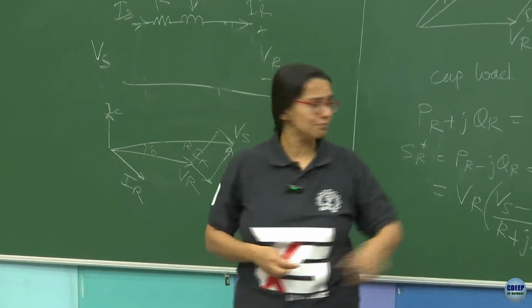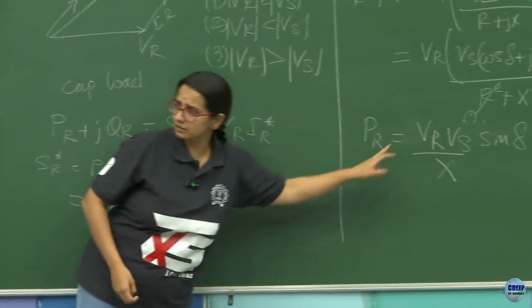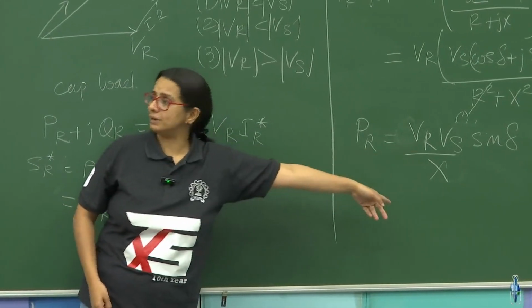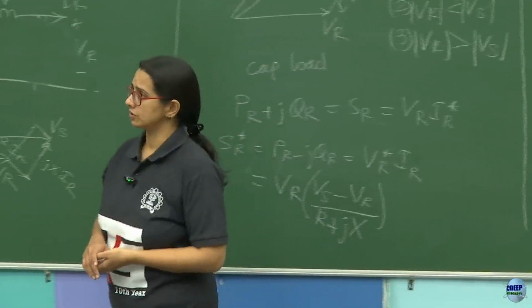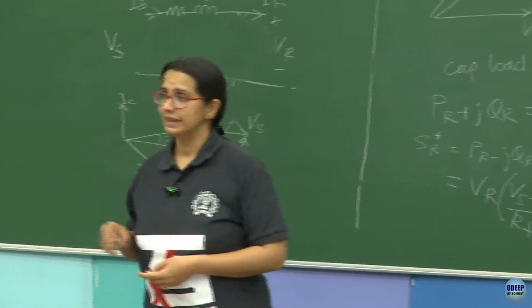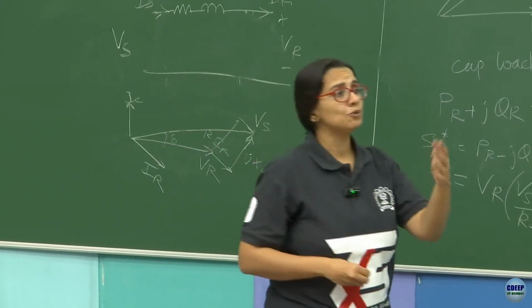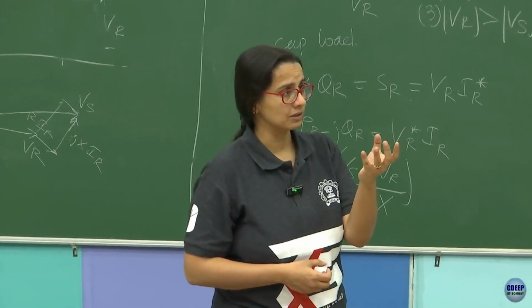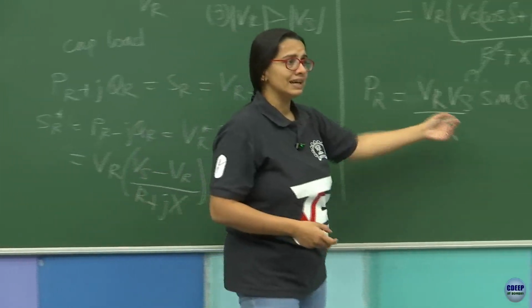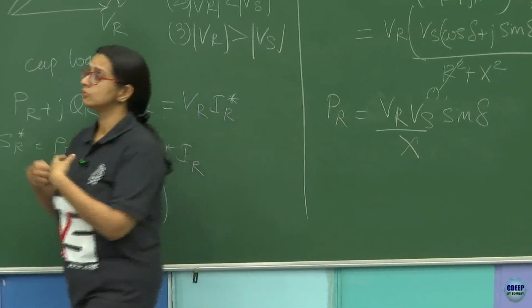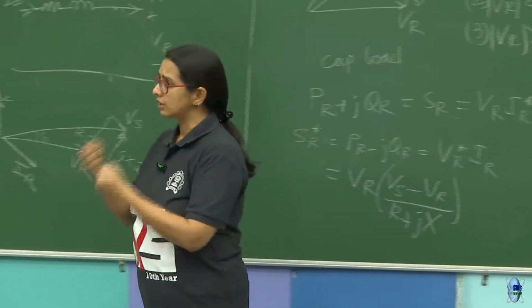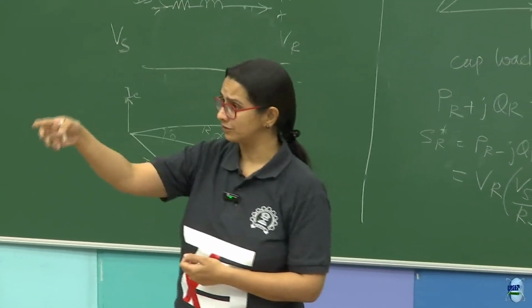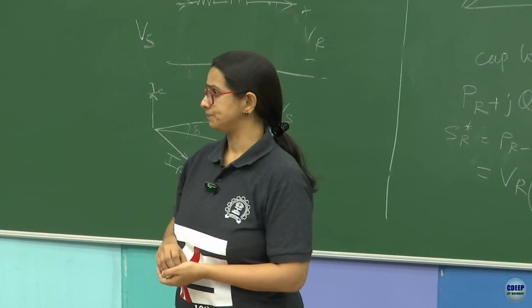And it is also dependent on the magnitudes there, correct? And it is dependent on the reactance of your transmission line. If you were to now put a series capacitor there, what are you effectively playing around with? This reactance will reduce, so you should be able to push more power across the transmission line. This is what one of your questions was.